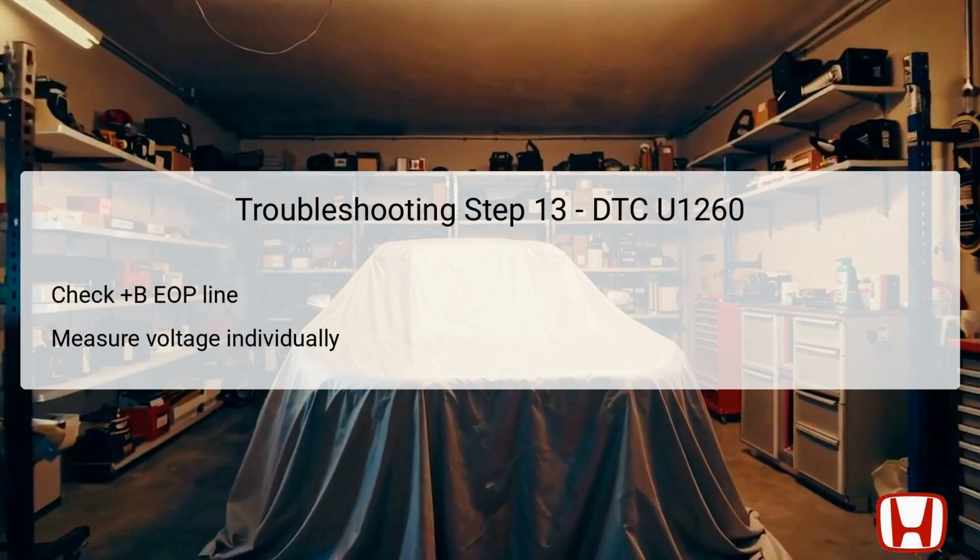Conversely, if there is an absence of voltage, this indicates an open circuit within the +B EOP line, which must be repaired. Continuity and voltage checks in this critical circuit ensure that the auxiliary pump can operate under the optimal conditions necessary for effective transmission performance.